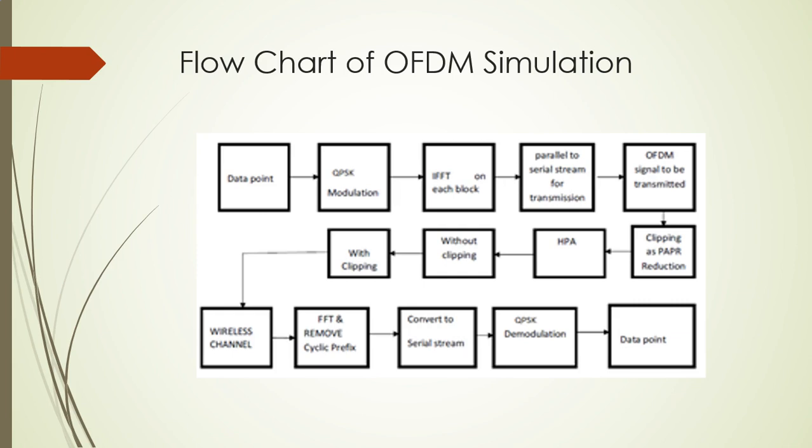The channel simulation will allow testing of clipping and effects of noise. When random data is added to the signal, noise will be simulated. The amplifier saturation is simulated by clipping. This takes care of a major problem, that is high peak to average power ratio.